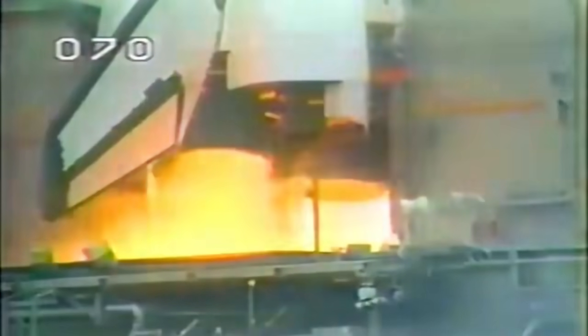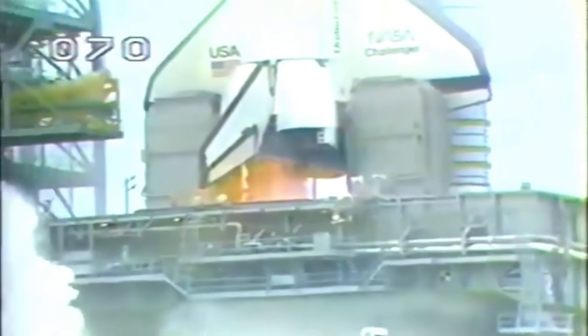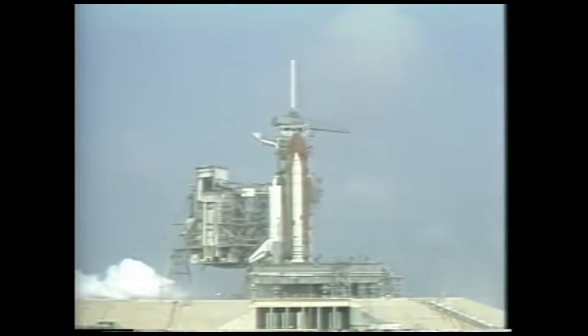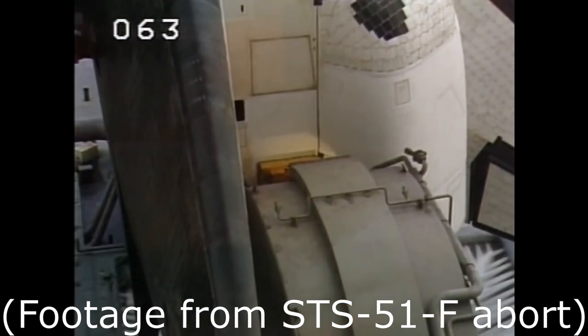For instance, the previously discussed STS-51F aborted due to a malfunction of an engine coolant valve. STS-41D, on the other hand, aborted at T-minus 6 due to a stuck LOX flow valve. Because the center engine hadn't ignited before the abort, but the others had, everyone really struggled to verify the state of the center engine. When the crew evacuated 20 minutes later, they were doused with water from the pad deluge